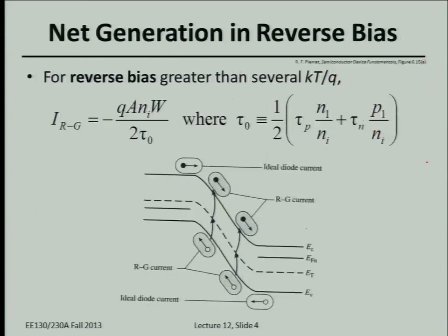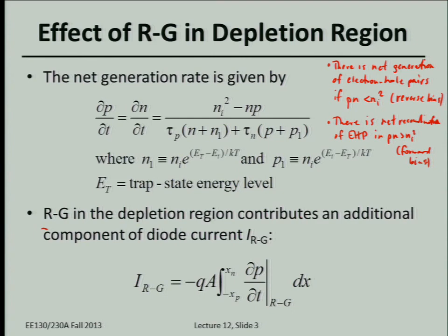See, on the next slide, all right. Well, I'll just draw it on the whiteboard. But if we look at the depletion region of a p-n junction, so this is sometimes a point of confusion. So I'm just going to draw the energy band diagram generic for a p-n junction. Okay, so let's say within the band bending region, that's the depletion region, you have generation. So an electron moves from the valence band to the conduction band. Okay, so you end up with a hole in the valence band and an electron in the conduction band.